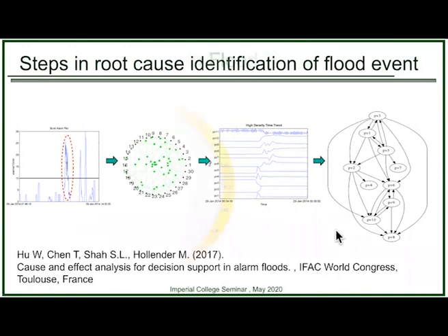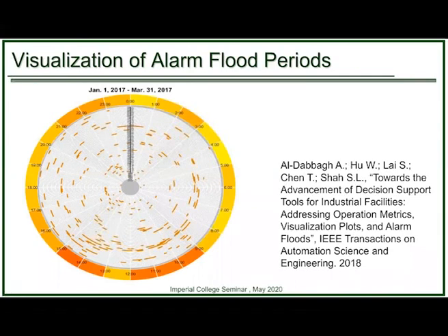All right, okay, so just the last couple of slides on visualization. The field of visual analytics is important and certainly useful in conveying information very effectively. Alarm data is binary, not interesting to display as a trend, but different measures of alarm, such as flood, can reveal quite interesting information. So what I show you here is alarm flood data over a 24-hour clock, this over 90 days.